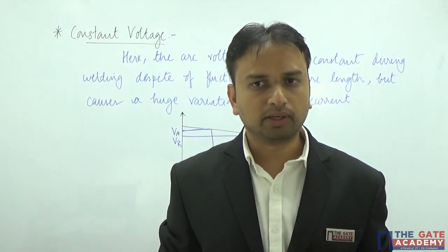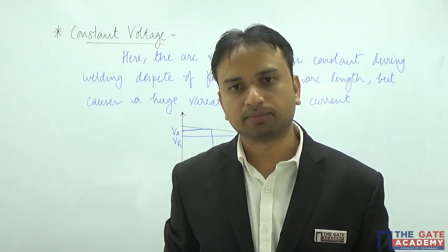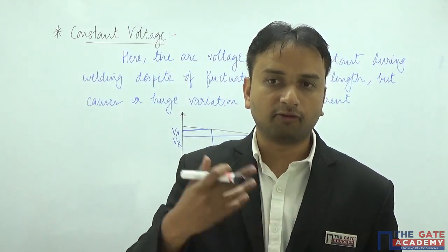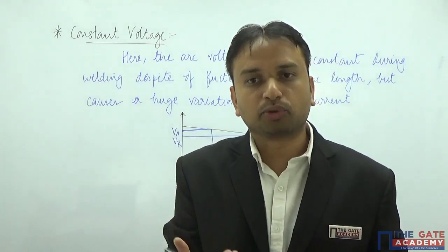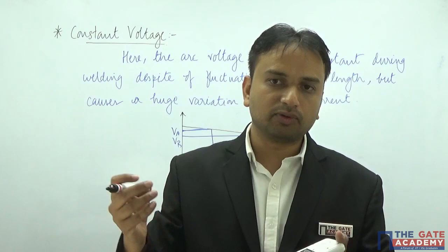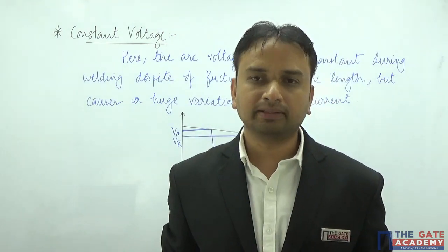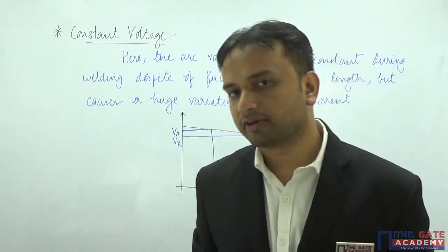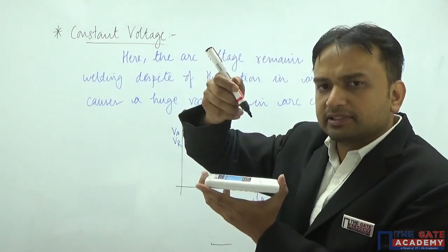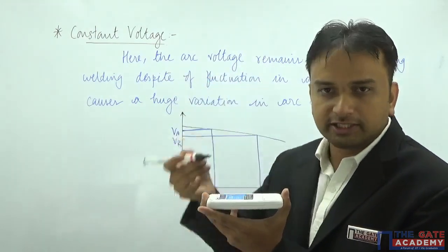I hope that you know already about the MIG welding operation and the SAW welding operation, and how the electrodes are present over there. The electrodes are present in the form of electrode wires, and they are wound over spools. The servo controllers are small wheels, and they keep on feeding the electrode wire. I hope that you have followed. Very good. Because it is a machine, the length is not going to change much, right?